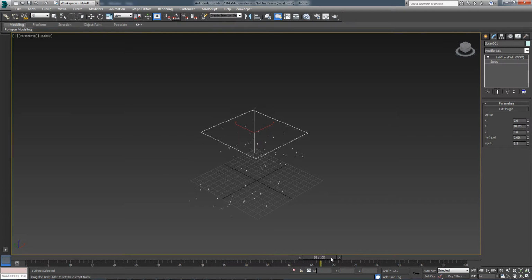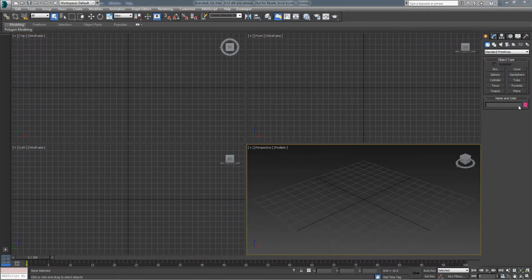Working with particles is a necessity of any 3D production, and creating something cool is a very desired skill. I want to show you how to control particle systems with Lab using a custom force field plugin. Lab implements custom force fields as a world space modifier, so we can just throw it on top of any particle system to create the desired effect.